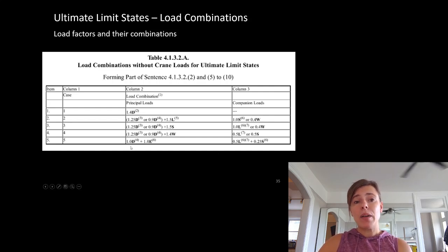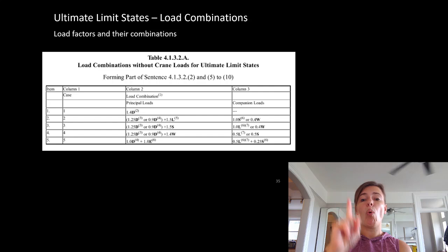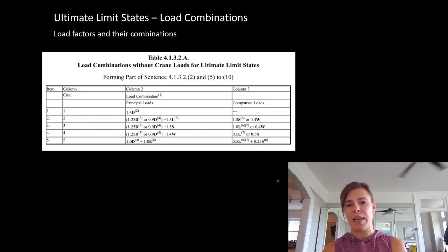And then seismic, we have to think about just dead and seismic load. And remember, seismic is a ratio of our dead load. And we have to think about dead load, earthquake load, plus live load and snow load. We do add them up here. So we have two cases here. We have dead and seismic, and then we have dead and seismic, live, and snow. The idea there being is that earthquake might be pushing down or pulling up. And so we want to look at the case where we have just dead and seismic, where dead's acting down and seismic's pushing up. So we have two worst cases that we have to think about there.